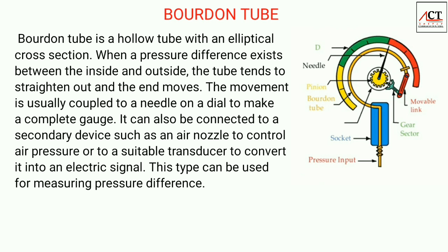This free end causes expansion and contraction of the Bourdon tube. The Bourdon tube has an oval-shaped cross-section and the sector is connected at the end of the Bourdon tube through an adjustable link. The gear sector is meshed with a pinion and on this same shaft, a needle is mounted. So if the pinion rotates, the pointer also rotates and shows the reading on the dial. The spring gets compressed when the tube has pressure inside it, and it helps to bring the needle to its initial position. When pressure is released from the tube, this stopper helps to stop the needle at zero.